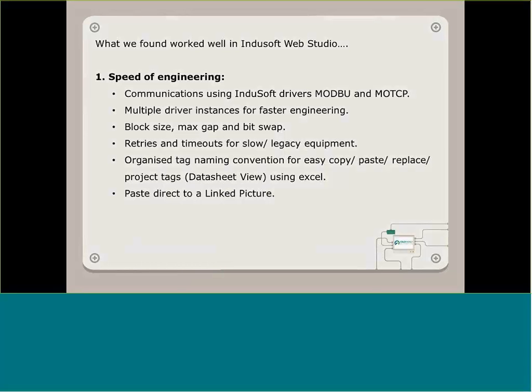We found that organising your own tag naming convention could be used for easy copy-paste, and using the replace option in InduSoft worked very well. Also copy and pasting into and from Excel works great, and pasting from pretty much any image editor directly into InduSoft was a massive saving of time, and time is money. So you could see in some of those screens they were pretty visually heavy with a lot of photos or pictures, and that's how we did it.